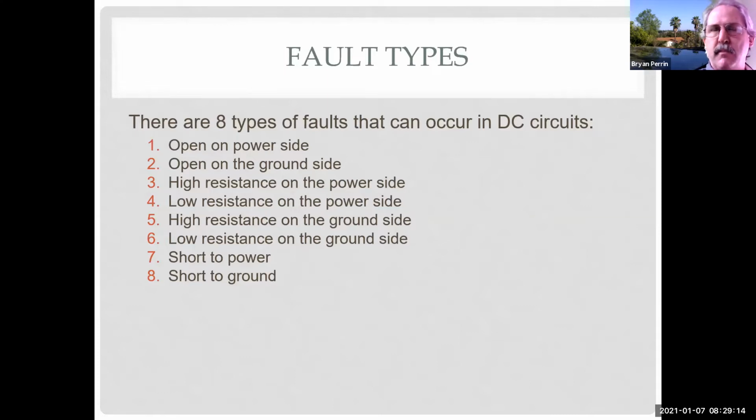Because I see stuff all the time I've never seen before. My contractor is here, who's a friend of mine, and his 58 pickup truck wasn't running, his fuel pump wasn't turning on. He has an aftermarket fuel injection system on it. Don't have any manual, never seen it before. I go over there and in less than 10 minutes, I figured out how the circuit works, with no schematic, and what's wrong. And he has a bad driver inside his computer.